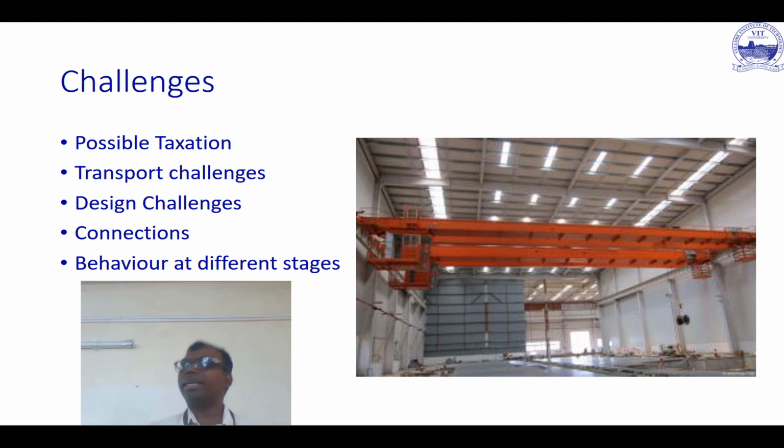you are going to find unnecessary cracks. And again, one more thing is when you store and transport, there is a different kind of load. When you lift it and place it into position, it undergoes a different kind of load. Once you place it, suppose it's post tension, you may apply some post tensioning to counter the self weight. Usually pre-stressing takes care of the self weight, and post tensioning is used to counter the dead loads which come. In fact, the video which I have will show you very clearly how this camber is formed in an element. We will have it in the next class.